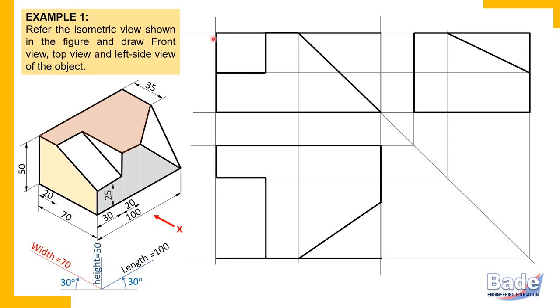This entire line is this surface. The height of this surface, that is 50, you should transfer by drawing end projectors. So end projectors here, end projector. So this is that surface. Why is it on the left side? This question is absurd because the three-dimensional diagram is in front of you and here you know that this surface is on the left side.